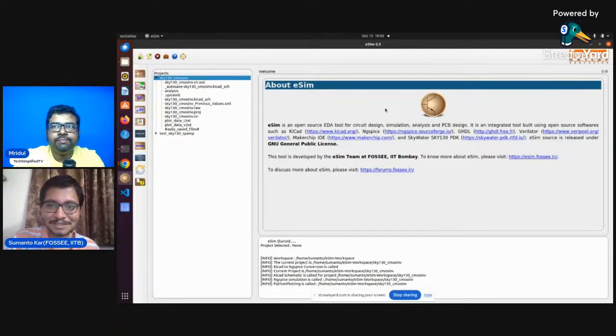Yeah, thank you once again, Vidul, for introducing and giving me the opportunity to talk about eSim and SKY130 PDK. So in this, as Vidul said, I will be covering how eSim is interfaced with SKY130 and how to simulate a circuit from eSim using the SKY130 PDK. As you can see my cursor, this SKY130 is also a part of eSim right now. I have already created a project using SKY130, and it's a CMOS inverter project. So let me open up the schematic.